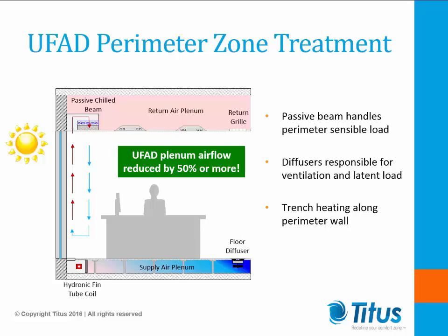Fin tube heating coils installed in a trough below the access floor provide space heating when required. A narrow bar T grill extends around the entire perimeter. The coils are usually installed intermittently, leaving inactive sections where room air can fall into the trough and supply the coils.